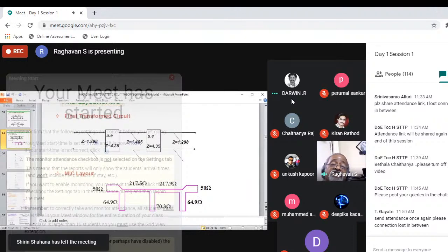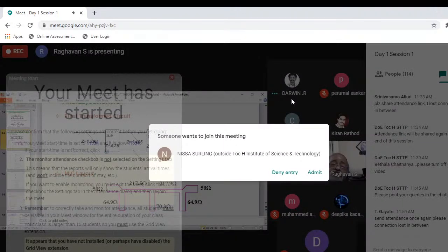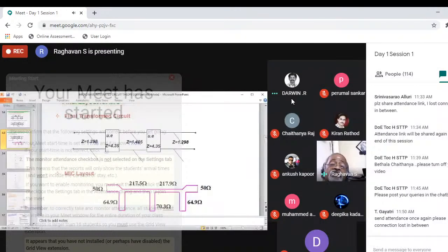And here there are two; I already told you there are only two methods of getting L and C. One is the high impedance, low impedance method, or stepped impedance method. The other one is the stub method. In the stub method, every part is lambda g by 8, whereas in the other method, the lengths will get changed. In the other method, the width will be the same. Here it will be different. Here every length is lambda g by 8, and the width depends upon the impedance.